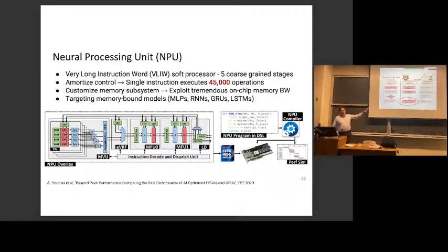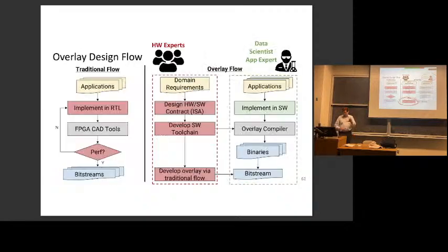No, there's no general processor in here. The idea is that you develop the overlay, and this is still implemented in an FPGA. The overlay architect wrote HDL, it goes in the FPGA, but that hardware has some ability to be controlled by an instruction stream. So it is a usually very unusual processor. And that very unusual processor can be programmed just using assembly language instructions, or if you've got a good software tool chain that can produce assembly language instructions from some higher level representation, then it could be programmed at a higher level. Does that make sense?